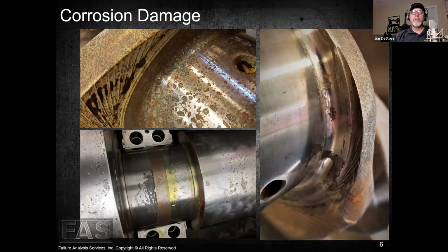The way the story was told to me is somebody was asked to spray it down and cover it up so it didn't corrode over the weekend. So apparently the individual was not a service technician, but more of a cleanup guy, I guess. So he went down there and he sees guys spraying parts down all the time with this Hudson pump up sprayer. So he grabs that pump up sprayer and he sprays the crankshaft down, covers it up. They come in Monday morning and it looks like this. Unfortunately, what he sprayed it with was a high concentration of the caustic cleaner that guys spray baskets of parts with that are excessively dirty before they push the start button. Yeah. So incredibly aggressive electrolyte, right?